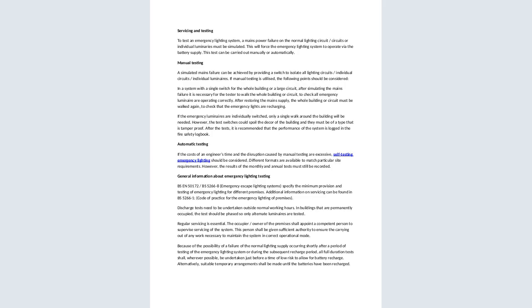And now another one is a fire safety logbook. Now, maintenance. How do we maintain? Finally, to ensure that the system remains fully in operation, essential servicing should be specified. These would usually be performed as part of the testing routine, but in the case of consumable items such as a replacement lamp, spares should be provided for immediate use.